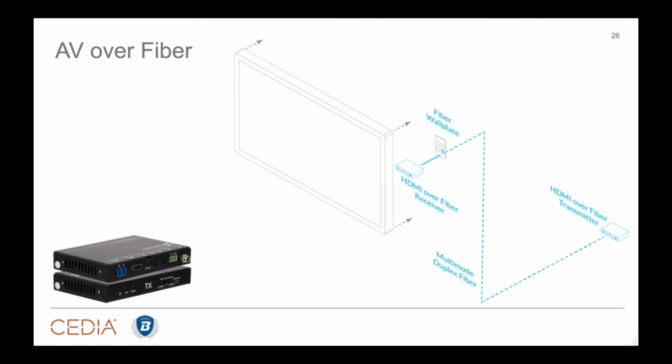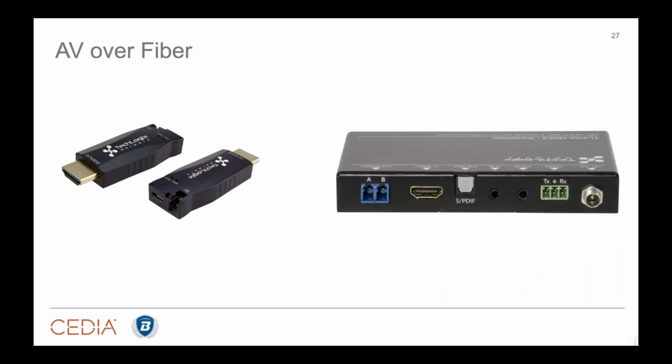The thing that I want to point out here is these are designed to handle that video bandwidth. They're designed to exceed the 10 gigabit performance where twisted pair cables would normally max out. If you take nothing else away, think about these: they look just like HDBaseT extenders, right? You've seen a twisted pair extender. What do they have? Video ports, audio ports, control ports like IR and RS-232. Man, these look just like the twisted pair extender you've been using for years. They just support more bandwidth.